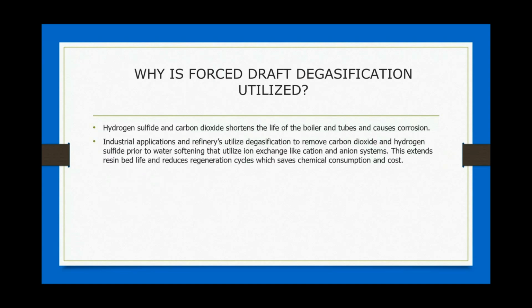Industrial applications, as David mentioned, and refineries utilize degasification to remove CO2 and hydrogen sulfide prior to water softening that causes ion exchange, like cation and anion systems damage. This extends the resin bed life by reducing regeneration cycles and also saves, of course, chemical consumption on the regeneration and operating costs. So you can look at degasification in this application for 2 processes. One, it lowers operating cost of the overall water process, and number 2, it preserves and saves the life cycles